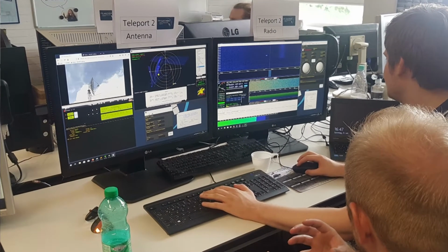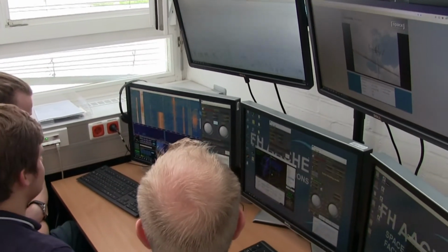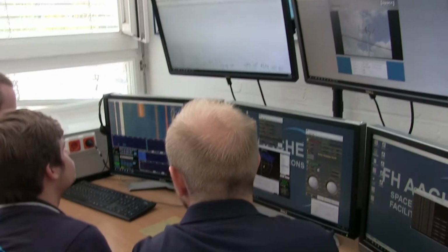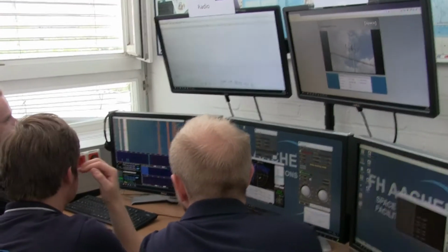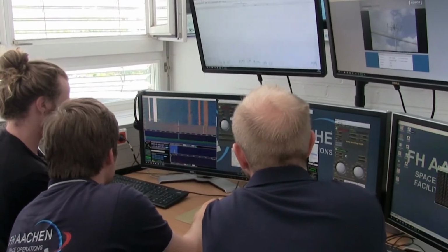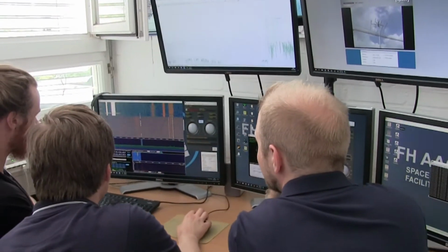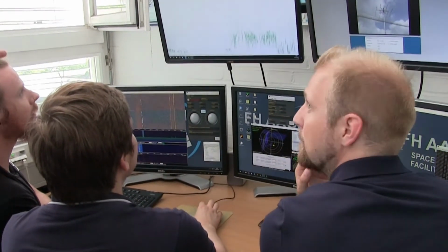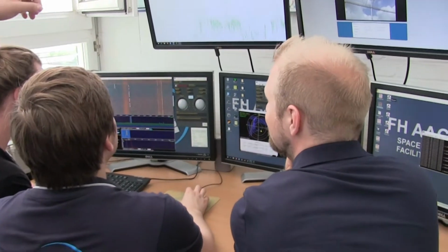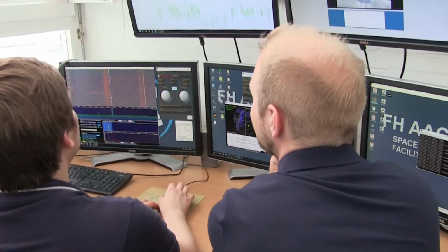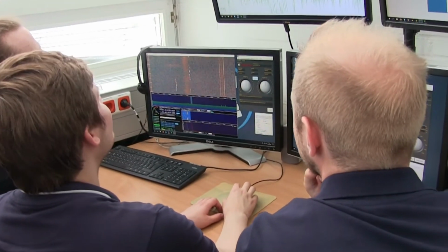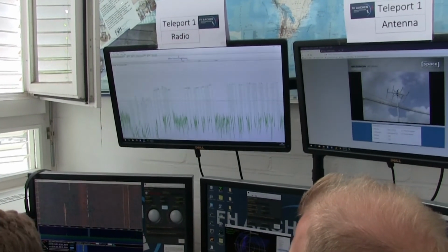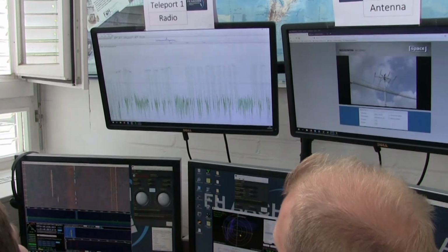When we now will track FunCube, NileSat and the weather satellites, you will definitely have Doppler. And then you need to correct the Doppler by yourself. Everyone has its own. But it's nice because it really gives you a direct impression about Doppler frequency, and after a while, it's very interesting to also hear the signal. And you get a feeling for it, if it's a good quality.